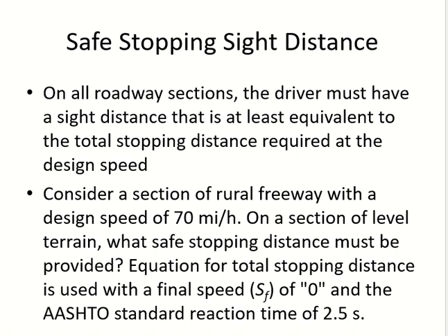Okay, so this is part of the design of the highway, that any highway, any street, any intersection, whether it's a point or the whole segment, you have to provide enough sight distance for the driver. And the minimum is the sight distance should be enough for doing what? Stopping. This is a minimum requirement. The sight distance should be enough for stopping.